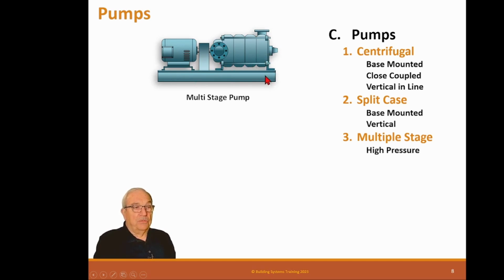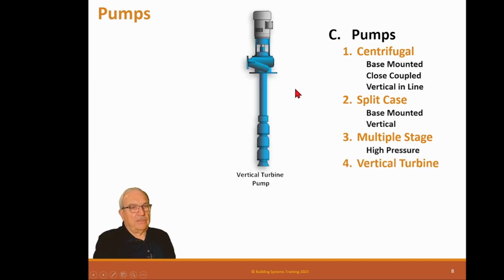Number one, really, really expensive. Number two, the suction comes in here. This impeller boosts it up so much, and this impeller boosts it up so much, and this one boosts it up, and this one boosts it up, and that's the way they work. They're high pressure by having multiple stages in series.